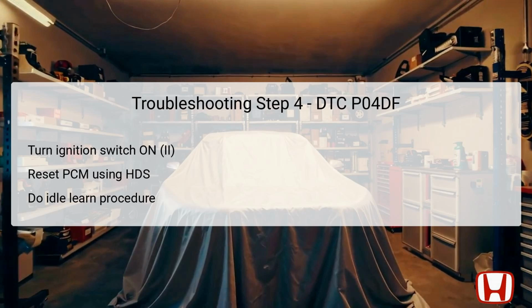Once the EVAP canister purge valve has been successfully replaced, the next step is to turn the ignition switch back to the on-2 position, allowing systems to initialize. At this stage, the technician will reset the powertrain control module, PCM, using the Honda Diagnostic System, HDS.